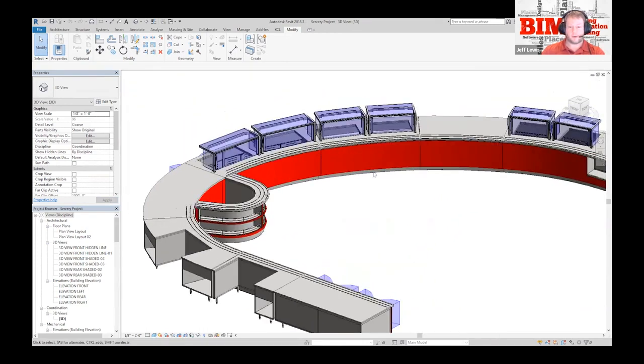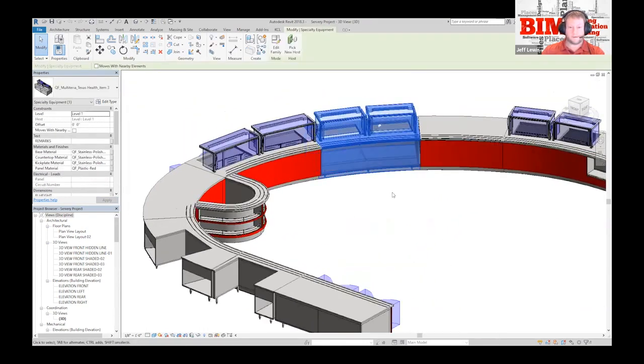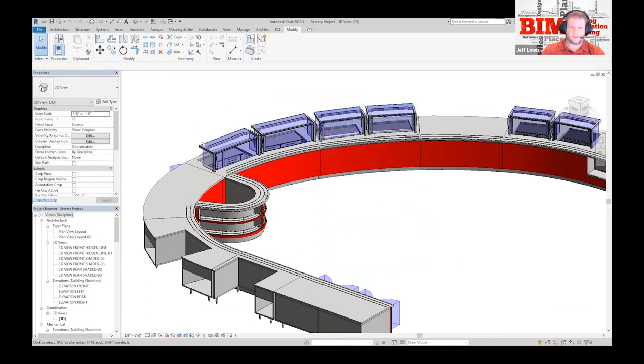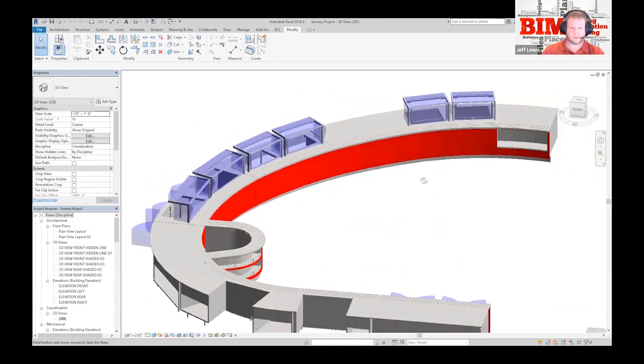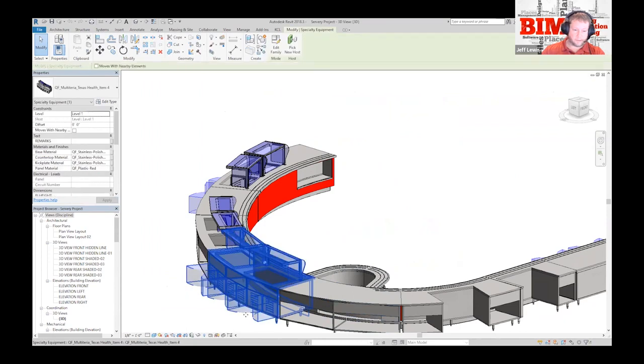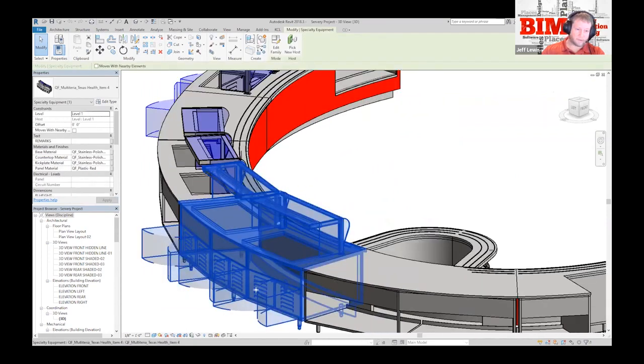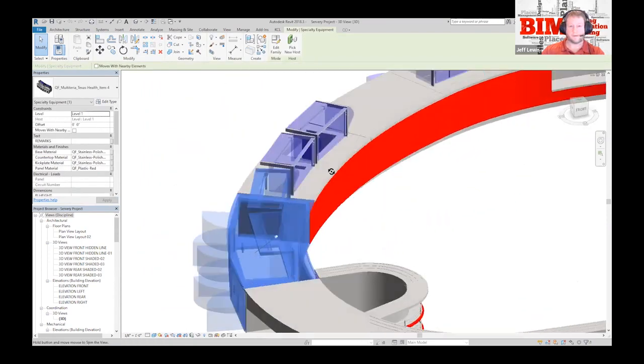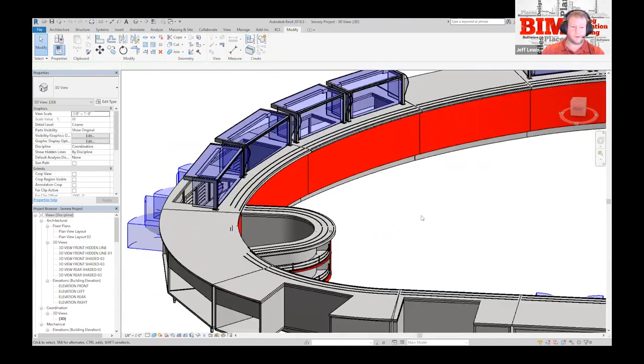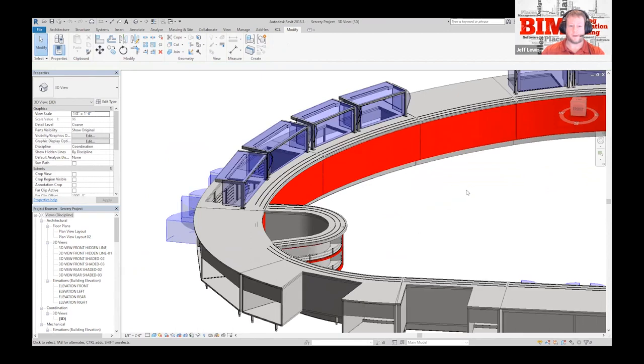Now let's go into a curved piece. We also notice on this that most of these sneeze guards are pretty much the same. Those you would want to build as a nest. This is where the upfront planning comes into play. You can build those first, come around, and in my case, I built the doors as a nest because they were going to be used in multiple places. When you build a nest, the more it's used in that same project, the less space it will take up.